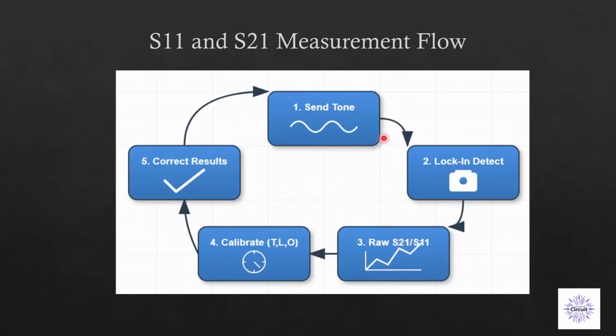So once I have this device that can measure S21 and S11, I need a calibration method to calibrate whatever loss or other inaccuracies I have in my system and cancel them from the results. So when I'm looking at the measured amplitudes, I only see the amplitude change caused by the device I'm interested in measuring, its S11 and S21.